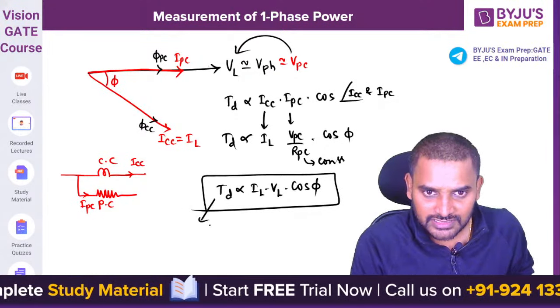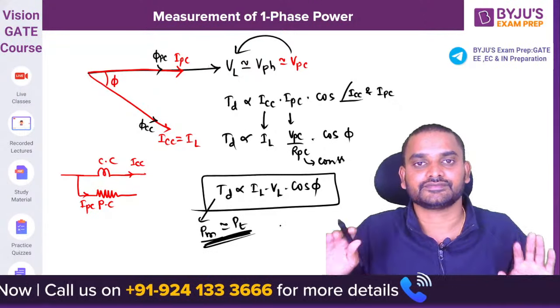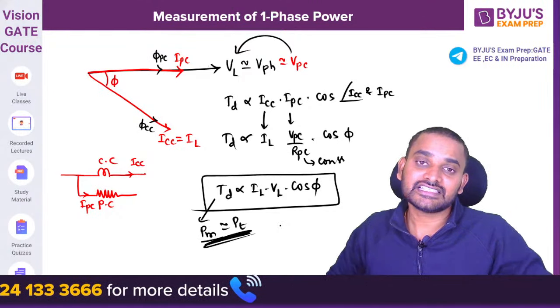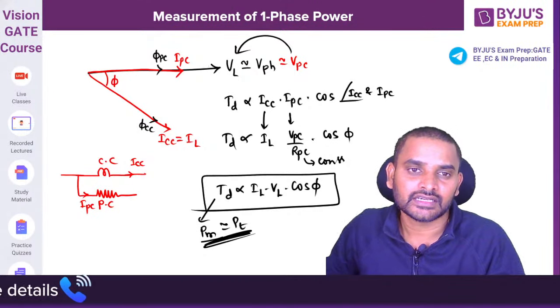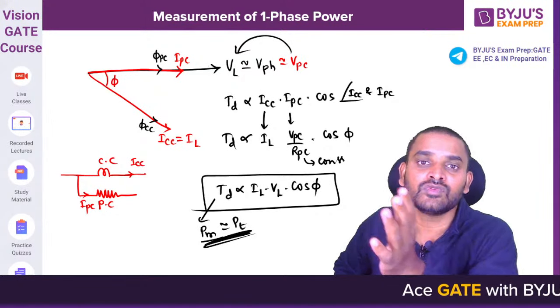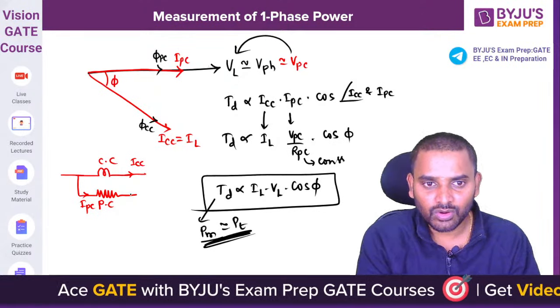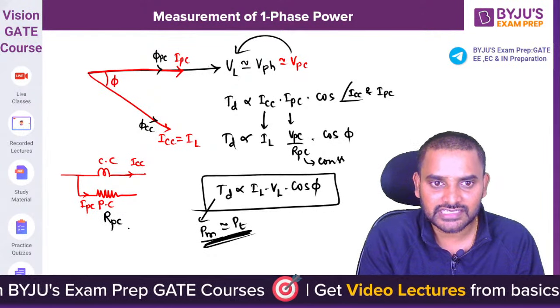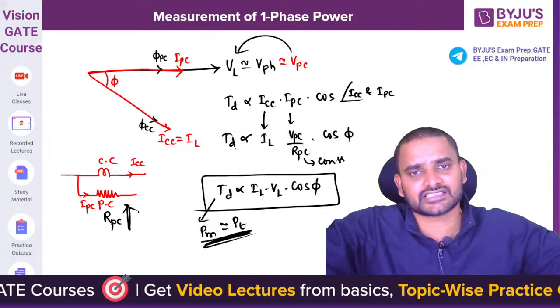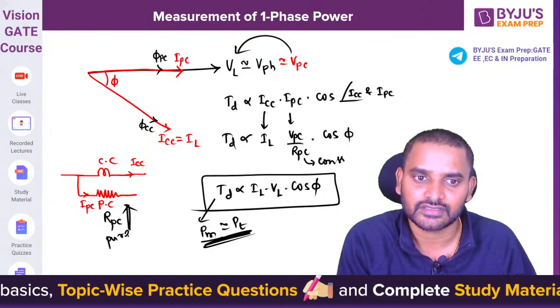This is what measured power. So measured power is almost equals to true power. This is how we will be getting the indication by the electromagnet moving coil instrument as almost equals to the true power consumption. It is possible only when you make RPC as very high or purely resistive nature. It is not to say exactly very high, it is purely resistive nature.